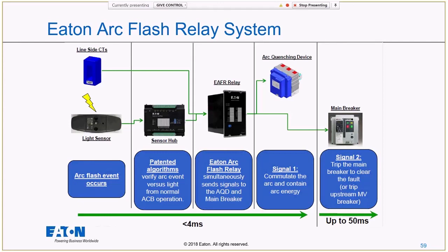And then it's also going to send a signal to trip the upstream device, but could be a fuse, could be a breaker, whatever it is you want to open the upstream device as well. That act is a slower act just in general, because of some mechanical features. So that's why, in the meantime, we try to quench that arc with that device and clear the fault. And that's generally how it operates, again, really, really quickly.